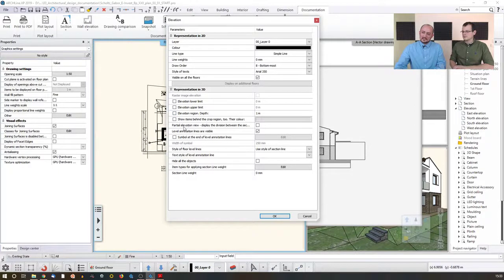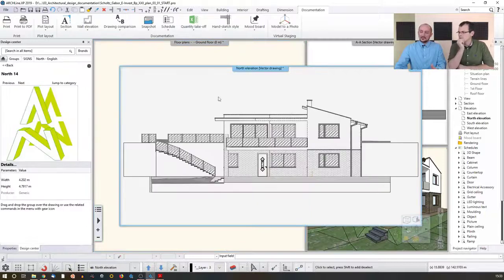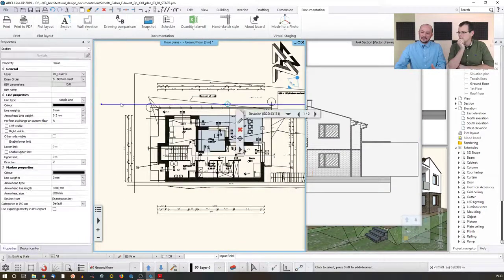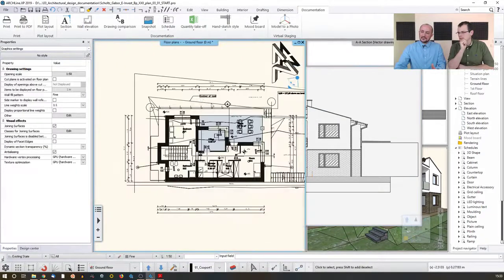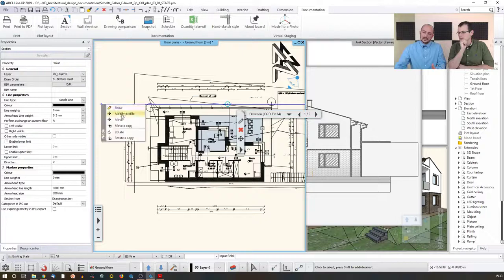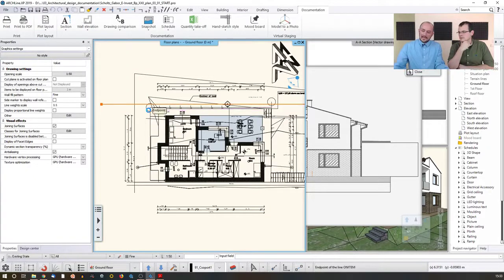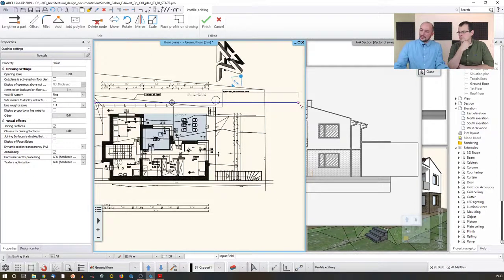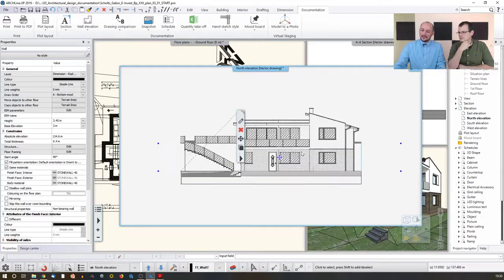So I just click on the partial elevation view, display the division between the section ends, and I click OK. Then I'm updating it, but there will be no change yet because the length is still the same. So I'm clicking here, and I'm changing the length. Sorry, I just clicked on the wrong option. So I just click here, I click on the endpoint, and I just would like to modify the profile of this whole thing, modify the length of it. Let's just make it locked and move until this point, and I do that the same here until, for example, this endpoint, and enter, and yes, create it, and then the software will make the limits trimmed out of this